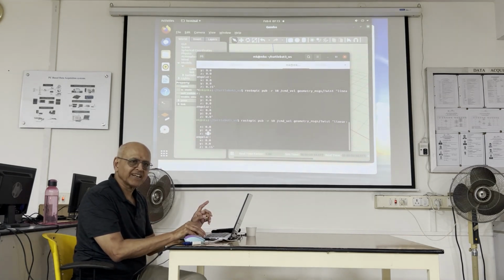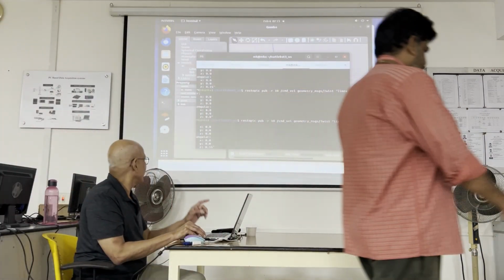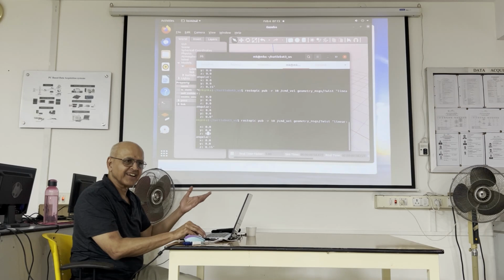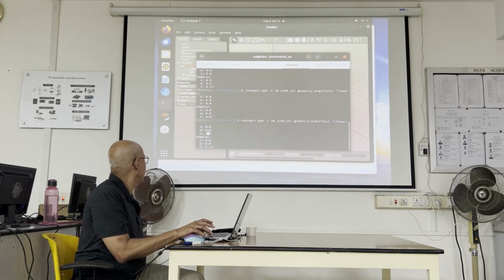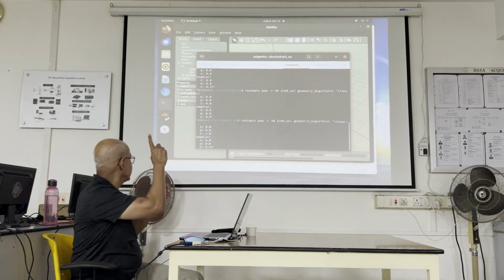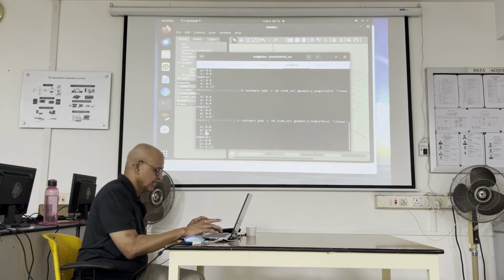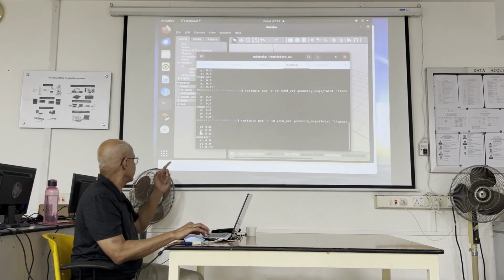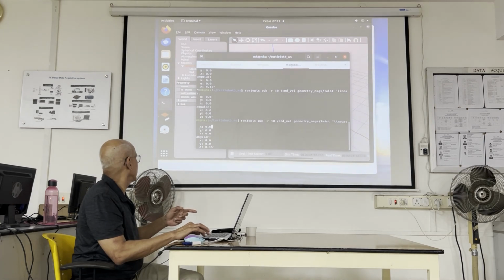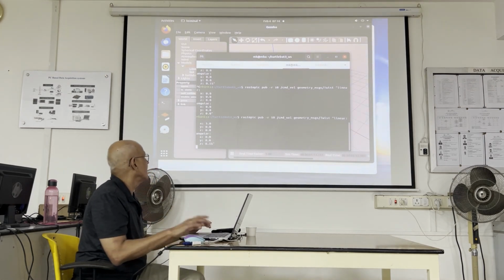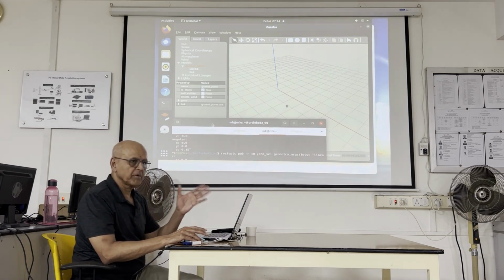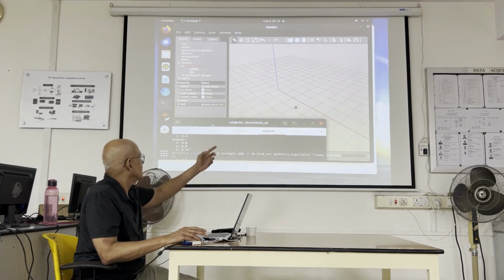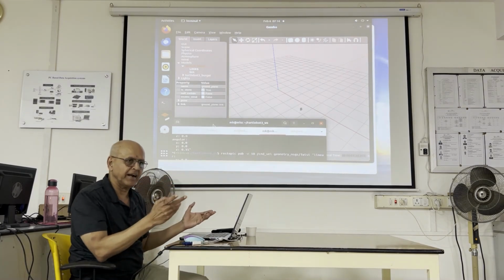I think I put it in the wrong place, right? I put it in X. And that's why it was doing that thing, because I'm forcing the robot to turn over. So Z is correct. Oh, I'm sorry, no. Z is correct. X is forward. Yeah, the speed is too high for it. So remember I told you that I thought I could run it at 0.4. It's too much for it, because yesterday I ran it in MATLAB. You saw that.